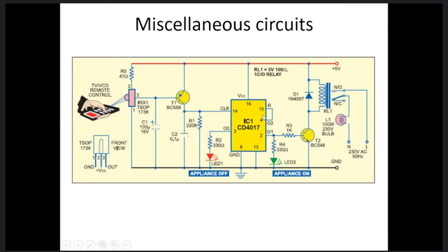When you see here, there are some hidden things, like in the CD4017. There is a very important reset function, and you have the pin outputs stage by stage, 2, 3, and 4. So 2, 3 are consecutive pins. You will get the output like 0, 1, 0, 0. Similarly, 0, 1, 0, and finally 0, 0, 1. So you'll be getting adjacent ones. And then the reset function will happen and it starts again.